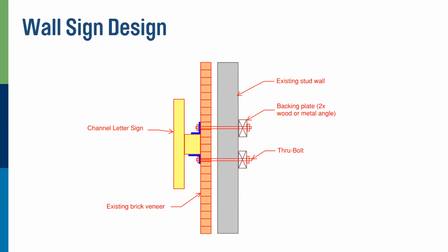And also the reality of your holes for your signs aligning perfectly with those studs is probably like 1 in 100. You're not going to hit it. So what do you have to do? The studs are usually 16 inches on center, maybe you have your hole 8 inches, or maybe it's a different spacing, maybe it's 12 inches on center. It's not going to line up with every fourth one.